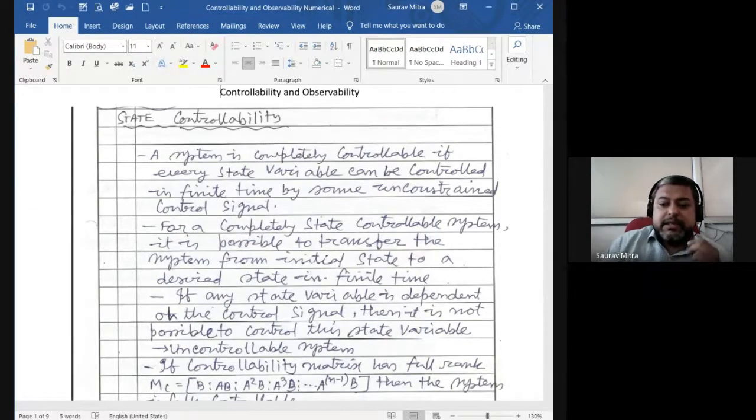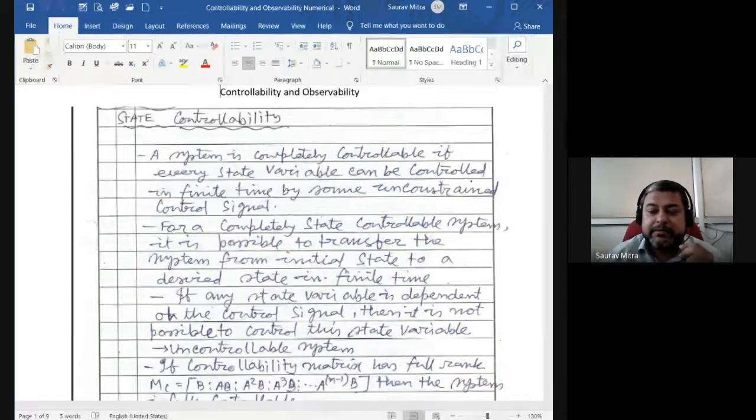So this was the format of the state variable model, and y(t) = Cq(t) + Du(t). If we can determine all these four matrices A, B, C, D, we can say that we have found the state variable model of the system. Some more numericals we will be seeing in the coming two hours of lecture, and that will be the end of the state variable model analysis.